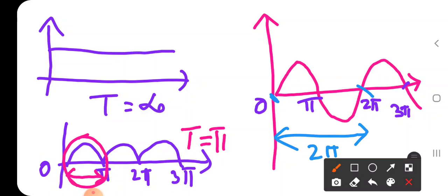But generally, while we are calculating average value, RMS value, peak factor and form factor, it is required to take the time period as it is for unidirectional and fixed quantities. Whereas in the case of bidirectional or alternating current quantities, we need to take only half of the cycle, because the next half cycle is similar to the first half cycle but in negative magnitude.